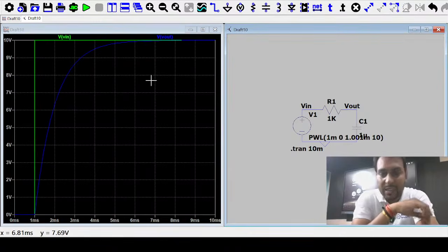If you remember the last class on Sunday, we discussed that the output rises exponentially with the help of dy/dx + Py = Q, the first order differential equation. On that basis you find the CF and PI, and you generalize one equation: Vout = Vout final + (Vout initial - Vout final) e^(-t/tau).